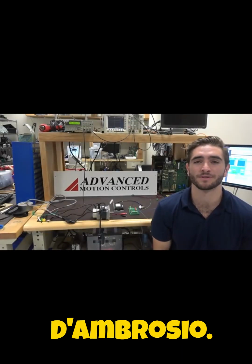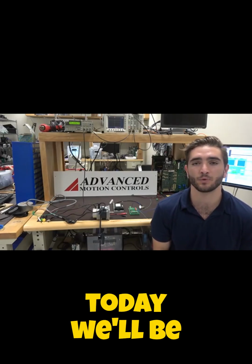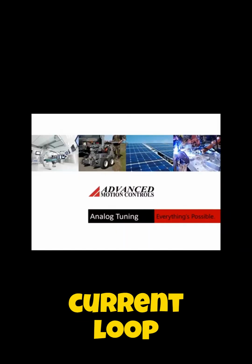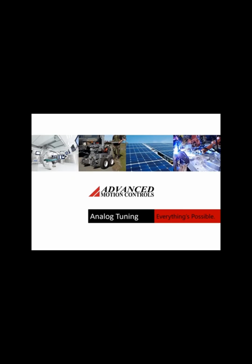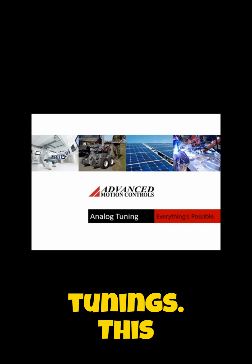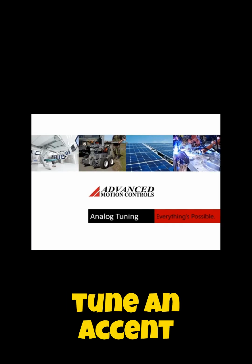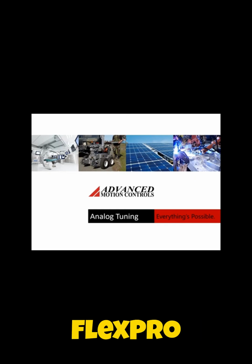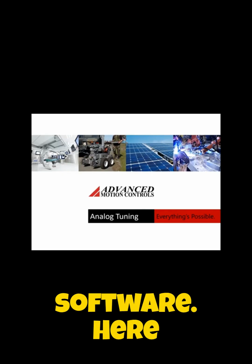My name is John D'Ambrosio. I'm a product and support engineer here at Advanced Motion Controls, and today we'll be tuning the current loop of an Accent analog drive. The default current loop gain settings on Accent drives are sufficient for most applications. Some systems, however, can benefit from alternative tunings. This video is intended to show how to tune an Accent analog servo drive. If you have a Digiflex or FlexPro digital drive, tuning can be accomplished through the software.